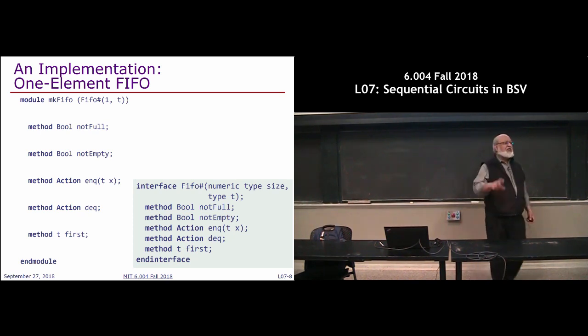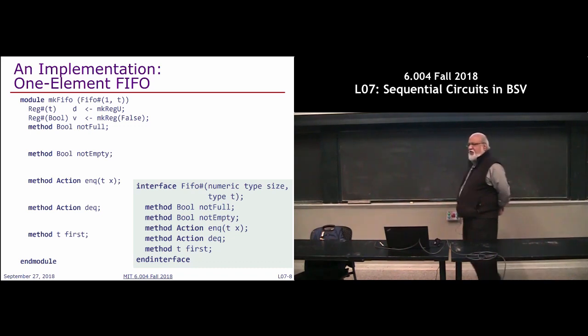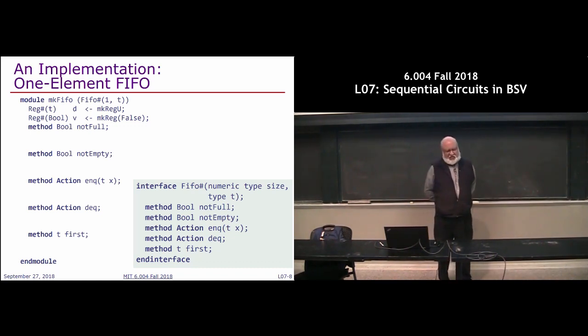You'll have one register to hold the value, right? So you have a register, make me a register, right? And now this time I made make reg U. U stands for undefined. Its initial value is not known, right?